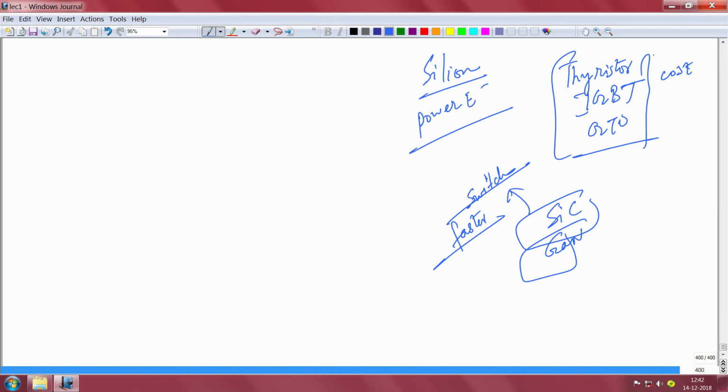Okay. So, here we will end the class today, just to introduce the different things, and I told you about different kinds of transistors or different applications of transistors where different types of transistors can be used. We started with power switching devices. I gave you some examples of how power switching is done, and the Baliga figure of merit, the relation between on resistance and breakdown voltage, I elucidated. I told you that silicon is much worse in Baliga figure of merit, still silicon is doing well because silicon is cheap and it's scalable very well, but new technologies are coming up for gallium nitride and silicon carbide that are going to be promising for things like hybrid vehicles, electric two-wheelers, your laptop adapters, solar energy panels.